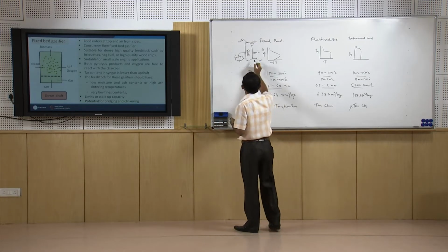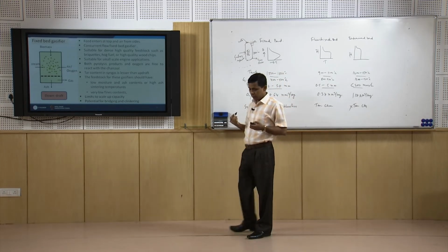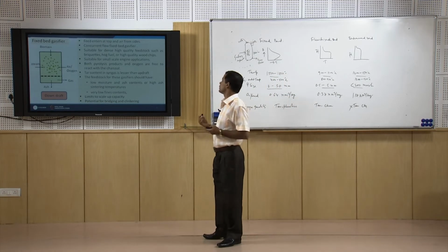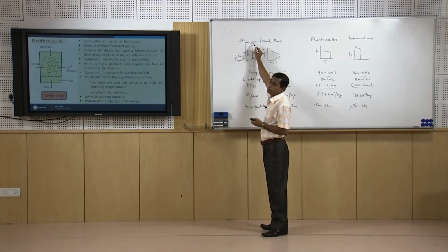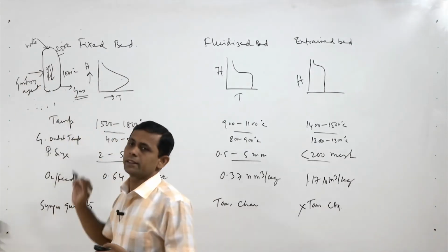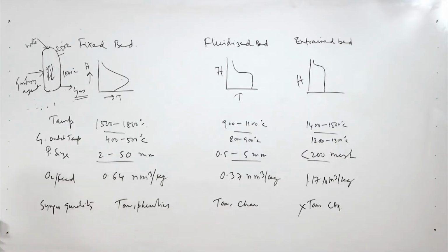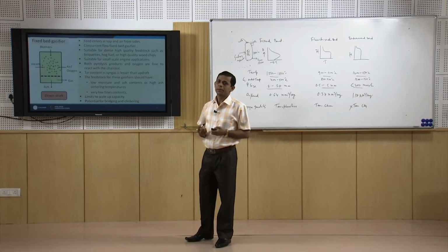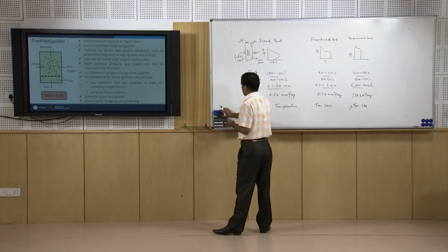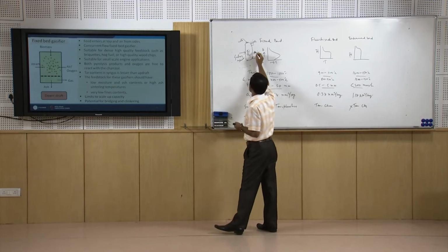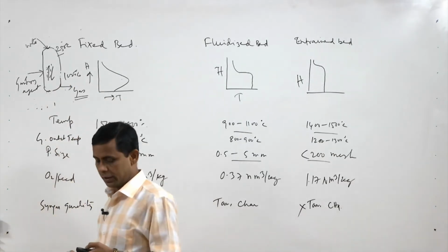So, the material and gasifying agent flow parallelly inside the gasifier and get more chance for contact and reactions. That is why the syngas is of better quality than that of the updraft gasifier, and as the temperature is also higher than 250 degree centigrade, tar content is less here. But the disadvantage of this gasifier type is the scale up problem. This gasifier has some scale up problem. The temperature inside this is around 1000 degree centigrade.